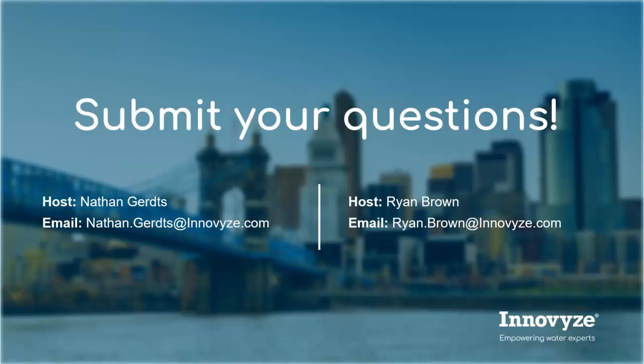Okay, this goes way back to my intro, but could you please explain how your product is faster and more efficient in calculating RTK values? Yeah, I know there's a popular feature with InfoSWMM and the RDII analyst, being able to automatically calculate those RTK values, but that's not a part of InfoWorks ICM. There would still be a calibration process needed to come up with those.